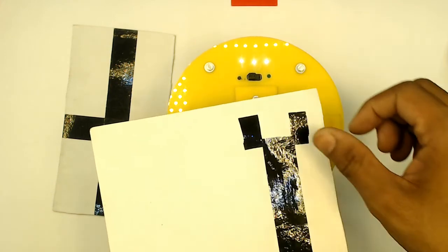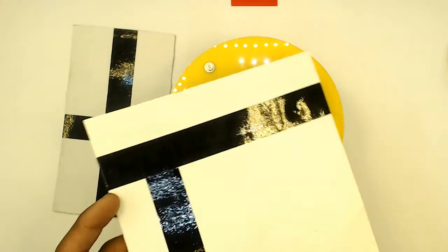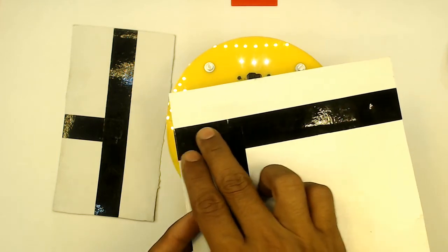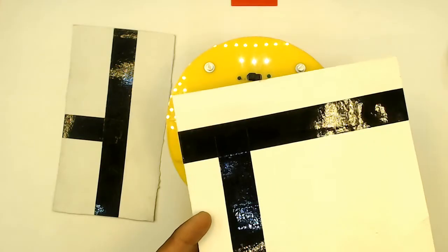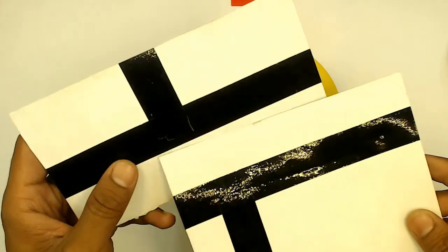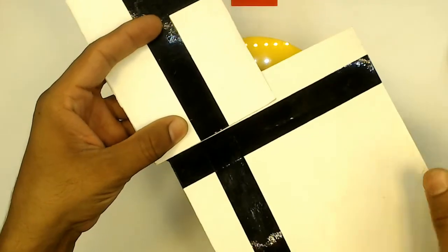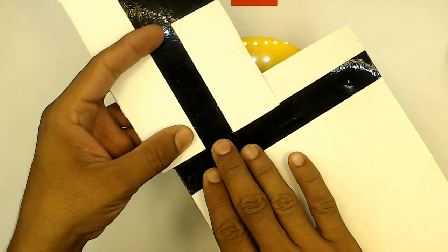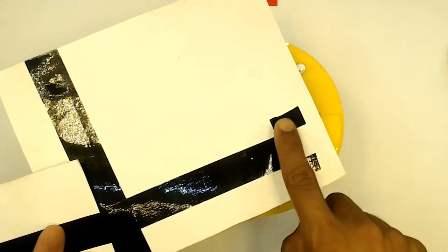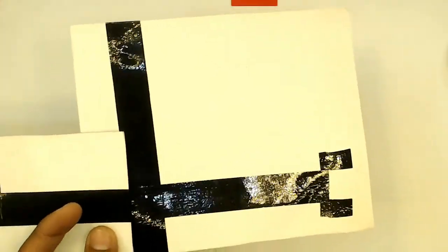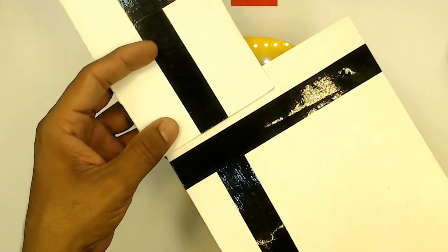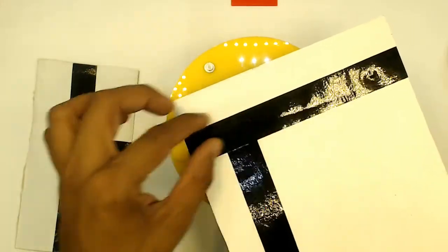The other possibility is that you can even take a black tape like this, so that whenever all the black surface comes in perpendicular to this one, it can detect this as a cross. Let me show you quickly. If I have a line like this, and you get a cross like this, then your robot may stop. I'm simply trying to take a unique condition for every kind of junction that it is about to identify.